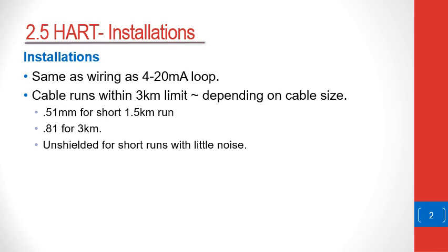For instance, if the cable is slightly thinner at 0.51 millimeter diameter, then it can only have shorter runs of up to 1.5 kilometers. If, on the other hand, the environment is noisy and unshielded cable is being used, then you might need to have shorter runs.